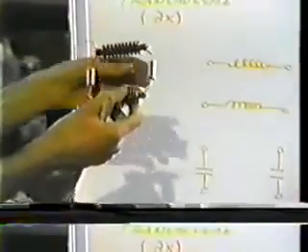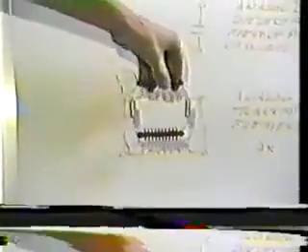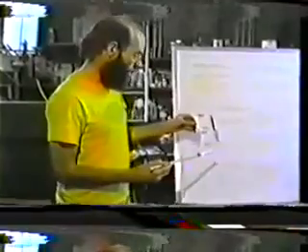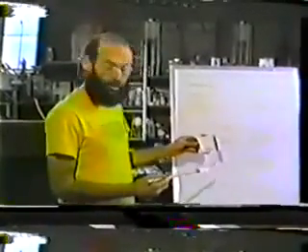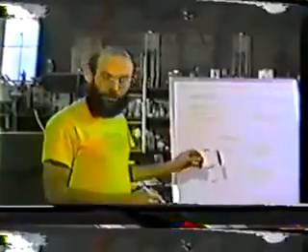And we have some radio frequency inductance coils of 10 millihenries, and we have some high-Q pulse capacitors of 0.047 microfarads. This constitutes one element of transmission. And of course we can propagate either longitudinally or transversely, and we're going to stack these elements up to symbolize and synthesize these 2 forms of waves, and then we're going to get in there with some rather unique detectors and some conventional detectors, and even use our fingers and determine exactly what's going on with these things and see how this correlates with our previous measurements of actual transmission structures and not their analogs.